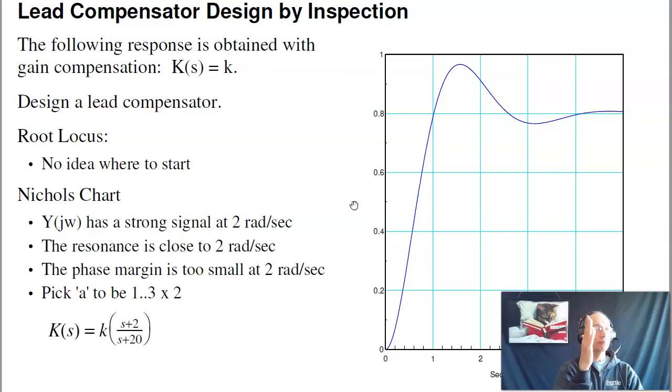Almost by inspection. The story behind that one is that the operators were saying it's not very accurate, and he had to ask them, what does accurate mean? Well, it's not bouncing. Sure, I can make it bounce if you want, detune it, but if that's what you want. That's something you can do just by inspection, looking at the frequency domain. Just given the step response, I know where the lead compensator belongs. So with that, we have lecture number 37, gain plus lead compensator design from the frequency domain standpoint.